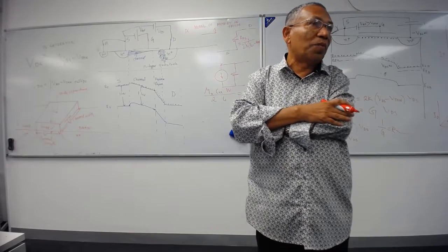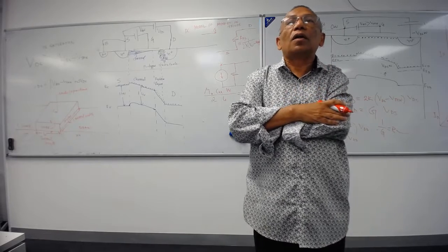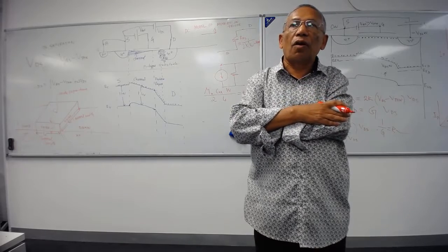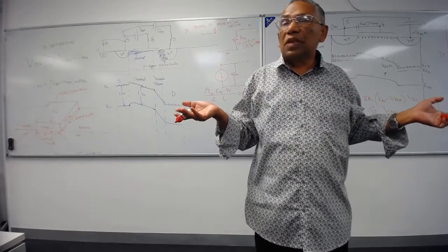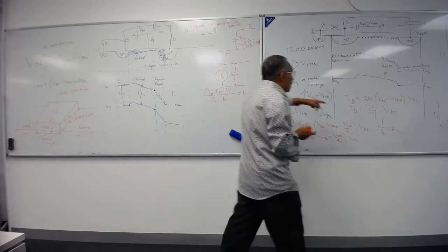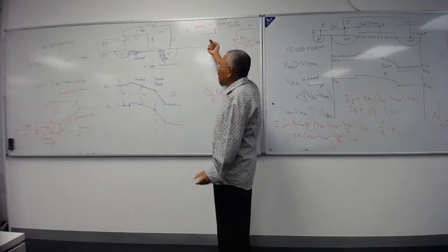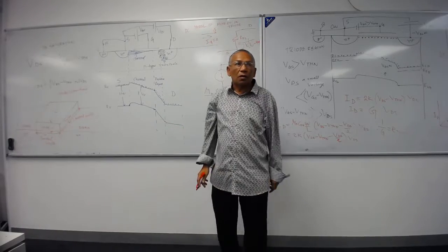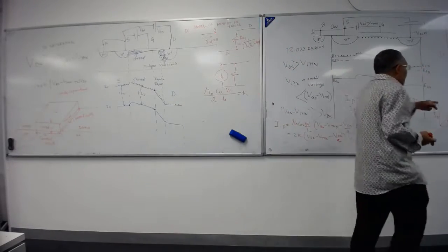That's an indicator that you made a mistake. So never use the beta given for the BJT in your arithmetic to solve for the condition of operation as a switch. So now, unfortunately, in MOSFET there is no beta, because there is no gate current. There is no current in the gate. Just now, he was asking me what is open. There is no gate current. IG equals 0. So beta doesn't make any sense. It is a voltage-driven device.